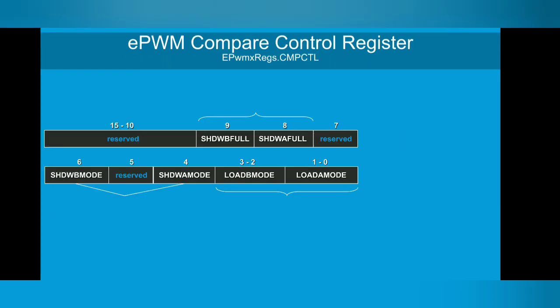We want to load the value from the background register into the foreground registers, and we want to check the status, whether your background register is empty or already filled with some value. So how can we check? First, we are loading the value from the background registers while the current period is executing.